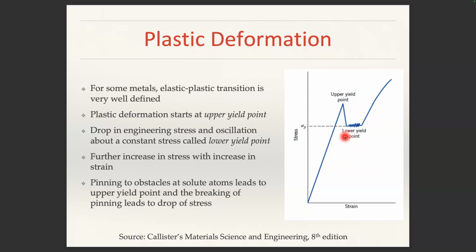You can see that the atom size of carbon is much smaller than the iron. And what happens is, these dislocations are encountering these solute atoms called carbon, in a very small percentage. Whenever they encounter them, they see some resistance, but then dislocations are strong enough to overcome the obstacles. That is when, once it overcomes, the stress required drops. Again, it will encounter another solute atom. Like that, all these solute atoms are causing these oscillations. And once there are enough dislocations, then your grain boundaries start offering resistance to dislocation motion, and hence you will have this strain hardening that is taking place, or work hardening.